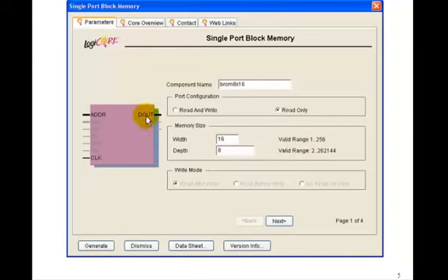Now notice that these block ROMs or block RAMs have registered outputs. That is, there's an address and D-out is the output, but there's also a clock input, which means that this D-out doesn't show up until the next rising edge of the clock. So unlike the distributed ROM and the ROM that we made in our VHDL program, where you put in an address and out comes the output, that is a combinational block, this is actually a registered output, so it has a clock.